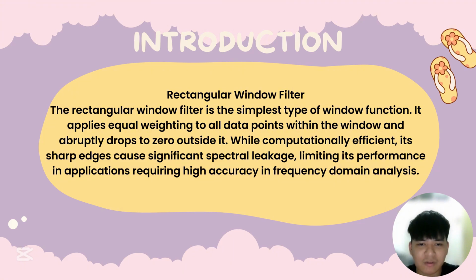The rectangular window filter is the simplest type of window function. It applies equal weighting to all data points within the window and abruptly drops to zero outside it. While it is computationally efficient, its sharp edge causes significant spectral leakage, which limits its performance in applications requiring high accuracy in frequency domain analysis. For the second